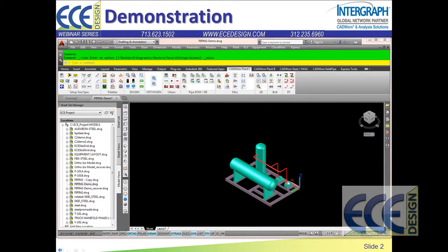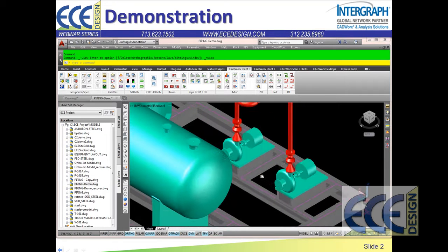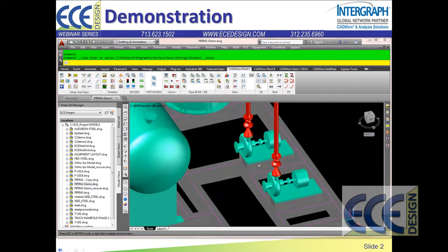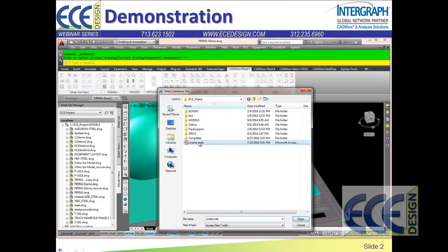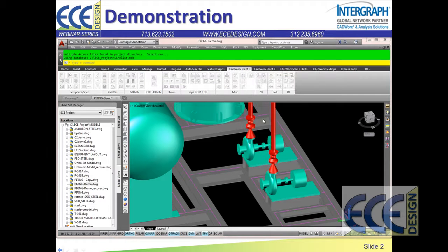Okay, well, let's move around here and go to work on the suction side of these pumps. So I'm just going to orbit a little bit so I can see both of these pumps quite easily. And I'm going to use my tool again to set my line number from process drawings. This line is going to be the 8-inch ASD 613. Now these nozzles on these pumps are 6-inch, but the flange we want to connect to on the bottom of this vessel is an 8-inch flange, and so the line's predominantly going to be 8-inch reduced right at the pumps to 6-inch.